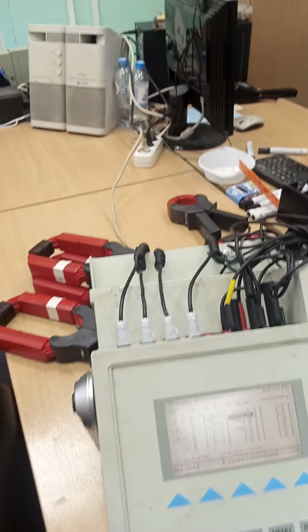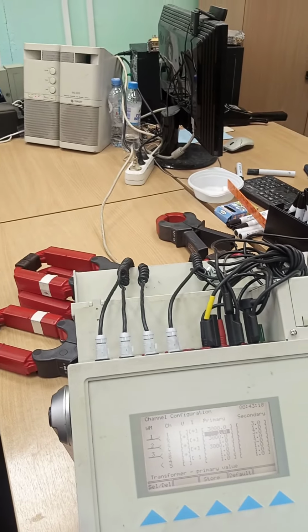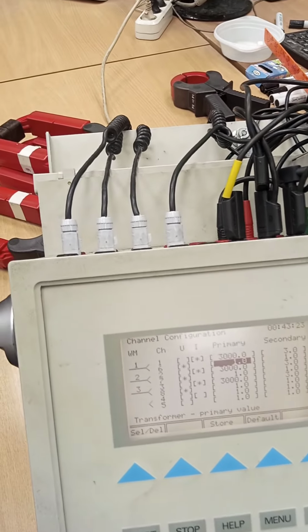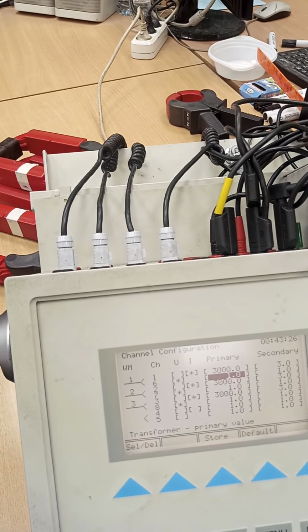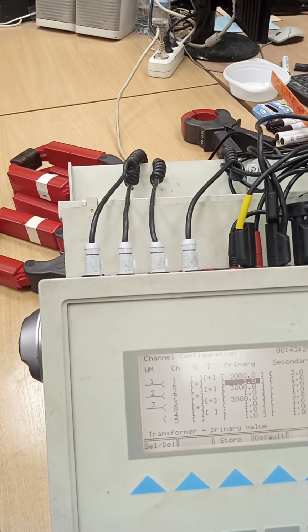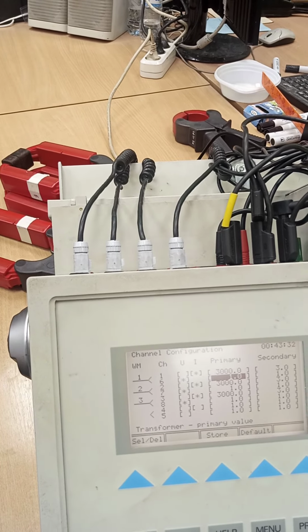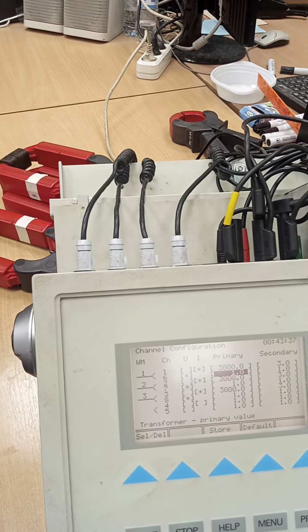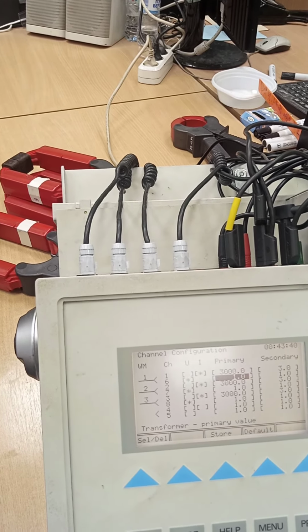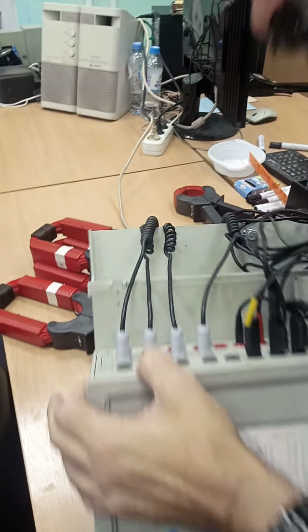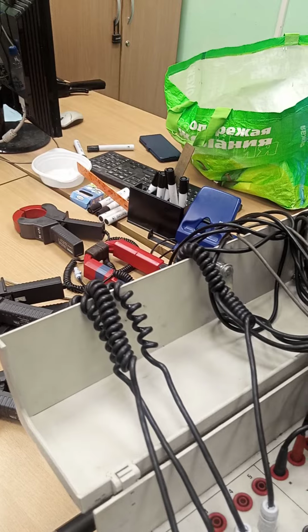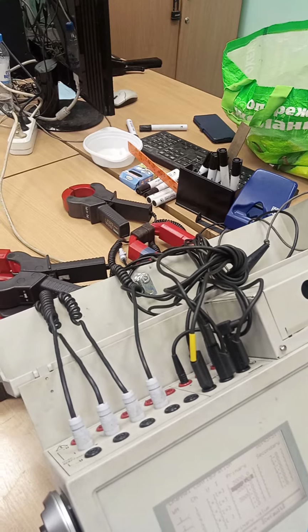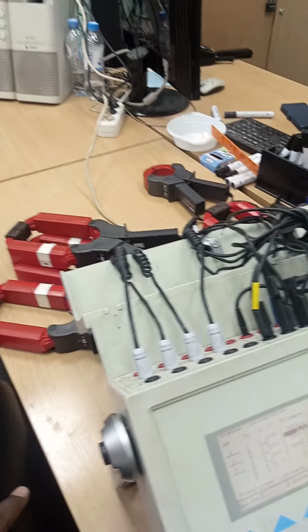If we will measure some, for example, high voltage network, let it be 10 kilovolts. If we perform measurements at a 10 kilovolt network, of course we cannot connect these clips to cables or to bars at 10 kilovolts. First of all, because of safety, because we will be killed, and the second reason is where is it? Maximum 660 volts, 600 volts. So we cannot connect it to 10 kilovolts.